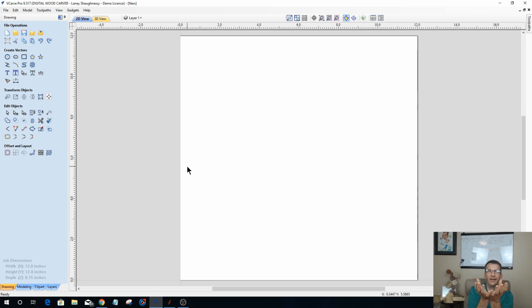You know, if I don't have a fourth axis or a rotary axis to create this, and all I have is my CNC table, then I could still create this part. I would just have to slice this sphere up and literally out of my 3/4 inch boards carve each individual slice and then assemble them together. I might have to do a little bit of fine sanding and things like that to clean it up after the glue-up, but I could still create that model.